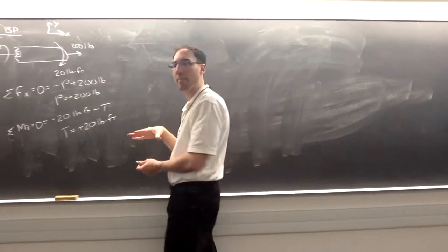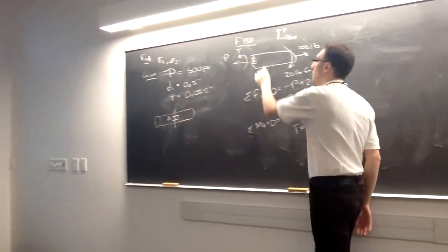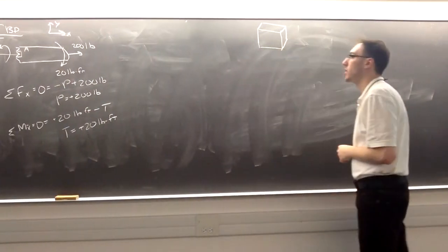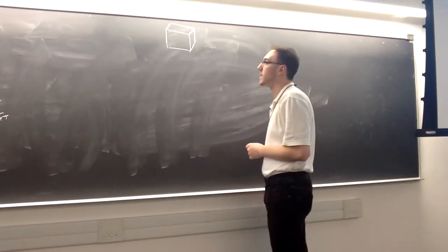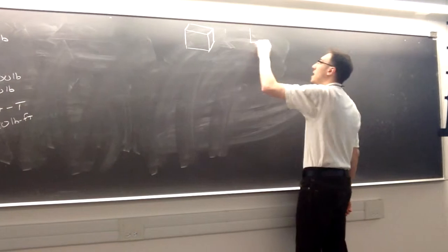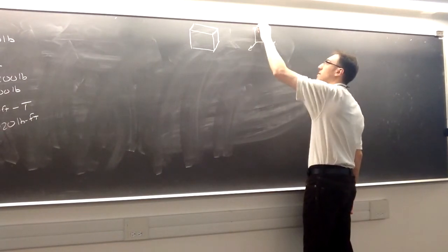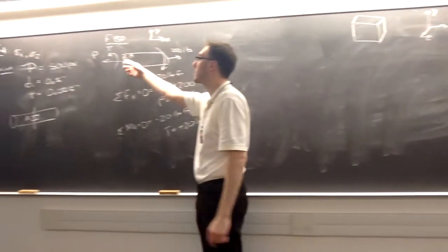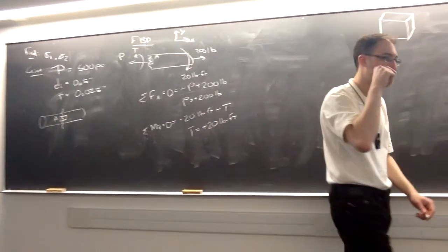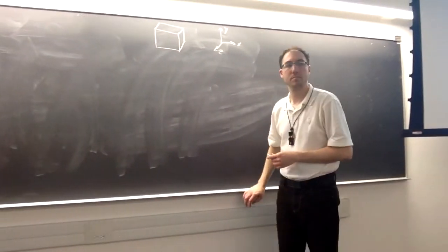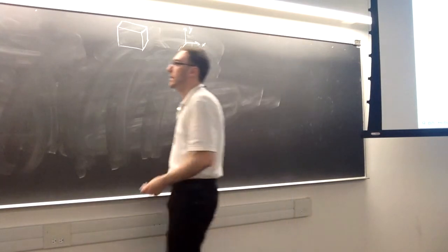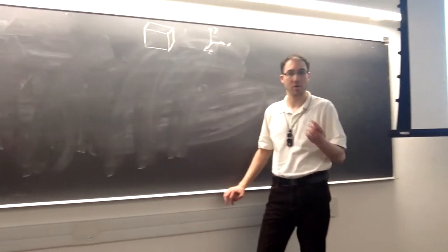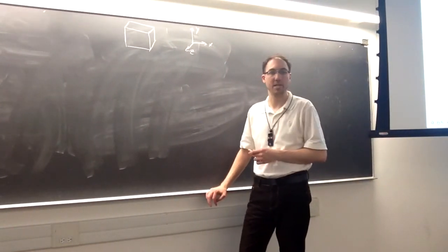So I now need to start assembling my stress state for that point A. I'll start here by looking at the internal pressure first and see what is the stress state that it causes. And for these pictures, I'll start assembling it with my x, y, and z coordinate system. So that cube is going to be aligned the same way as that stress element. All right, so due to pressure, on what faces will the pressure cause stresses, and what type of stresses will we have?